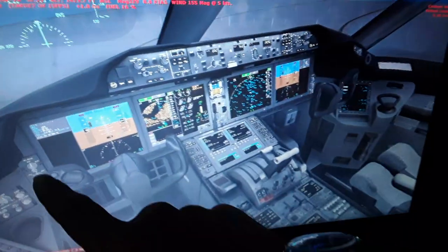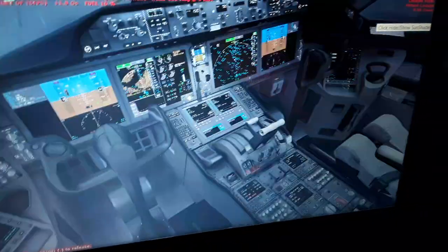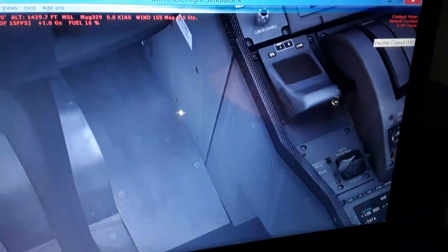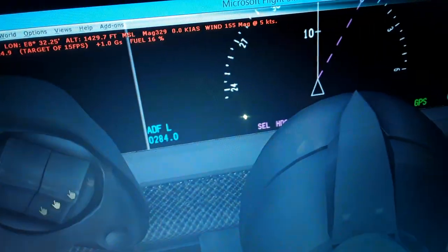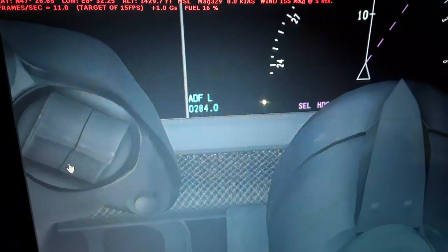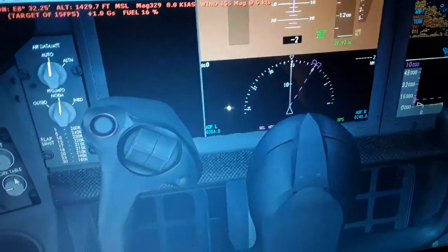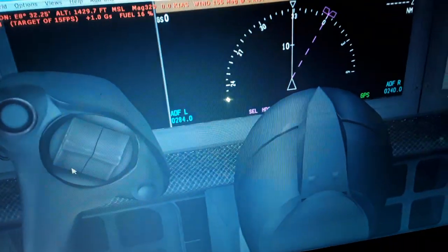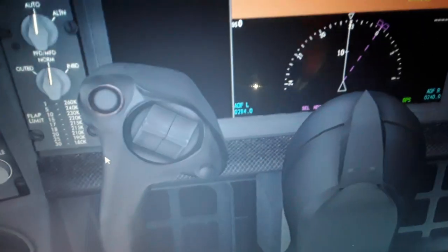So we have over here the horizontal stabilizer trim, and also the normal and the alternate, which is manual stabilizer control. When flying manually, you use the elevator for climb and descent in the Boeing aircraft. Like this, pitch the nose up when flying, or trim the elevator up, and pitch the nose down, or trim the elevator down like this. So you can see the elevator trim.